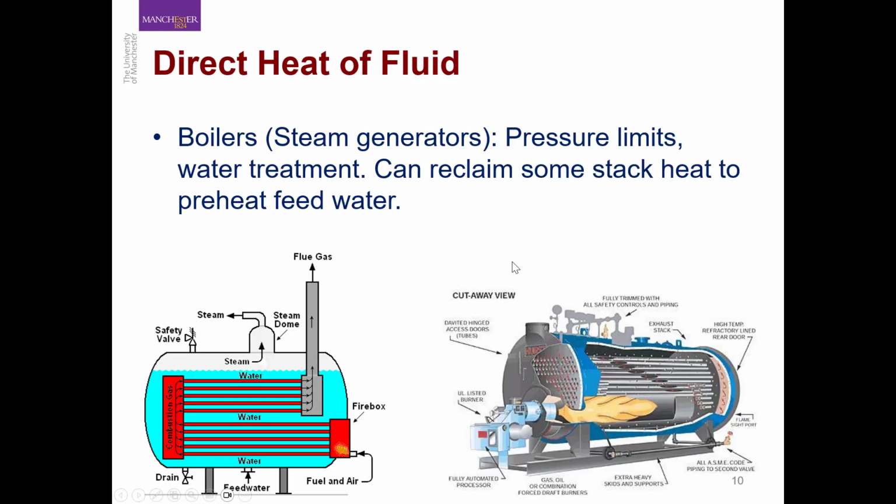And these direct fire heaters are also very common in, for example, boilers or for low scale steam generation. Normally, how we use them, again, we have the fire tube or the firebox where the fuel is being burned with the air, and then you have these tubes that are immersed inside the process fluid that you want to heat, and in the shell you have the process fluid.